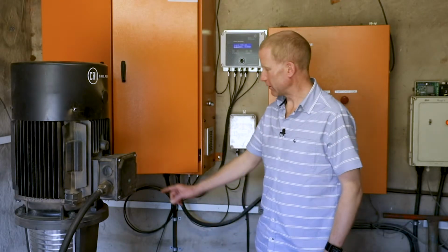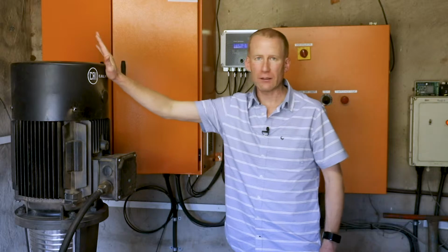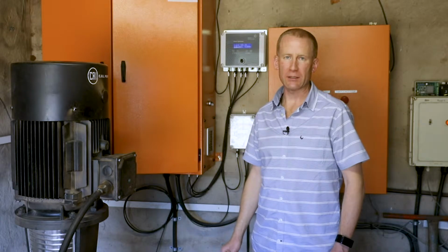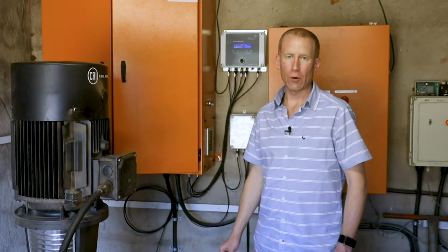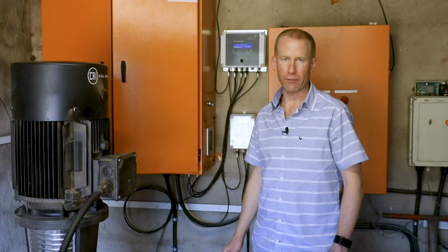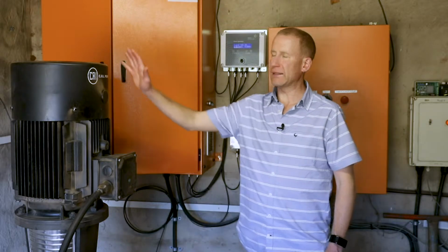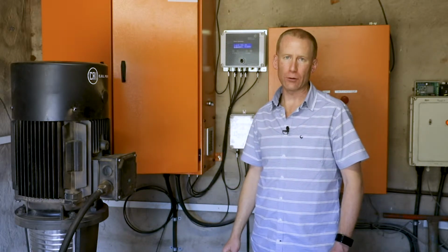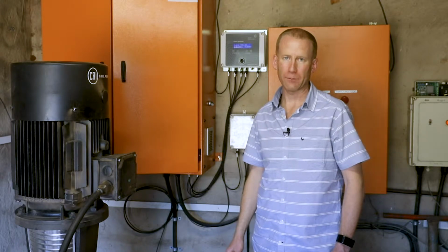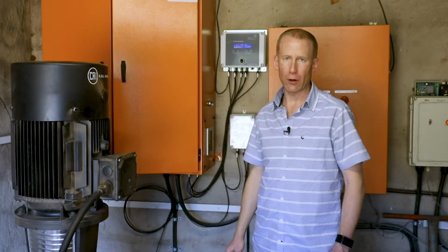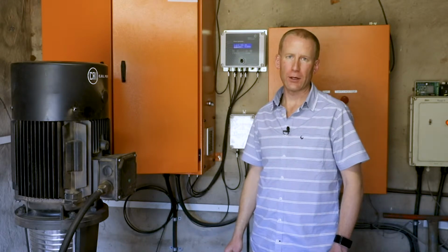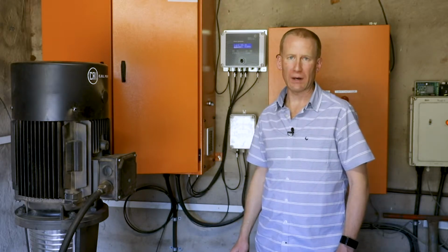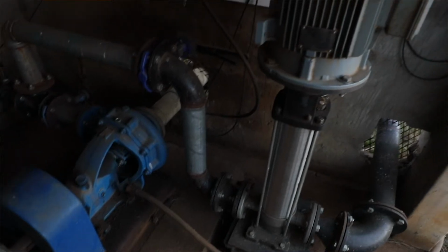The system also monitors the pump outlet pressure, power consumption by the motor, and flow rate through the pump. It uses these parameters to calculate the hydraulic power, which is the differential pressure multiplied by the flow rate. It then divides that by the electrical power that's consumed by the motor to calculate the overall pump and motor combined efficiency. If the efficiency is very low, then we can perform further analysis to determine the root cause of the low efficiency. Low efficiency can be caused by an incorrectly sized pump or by a worn out pump.